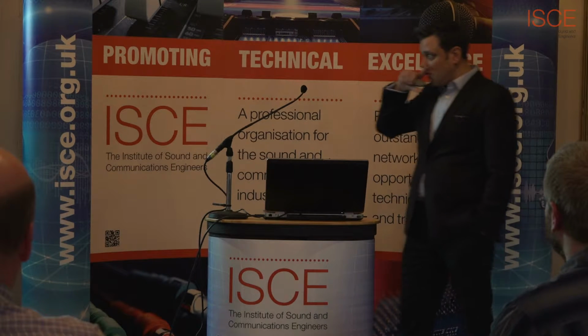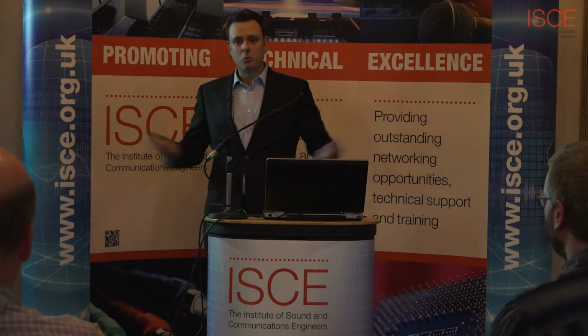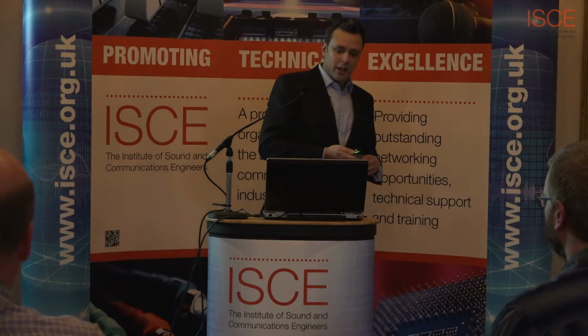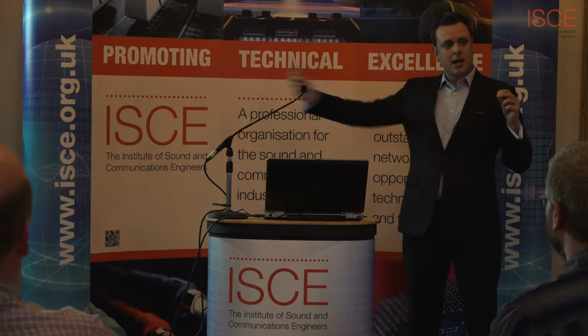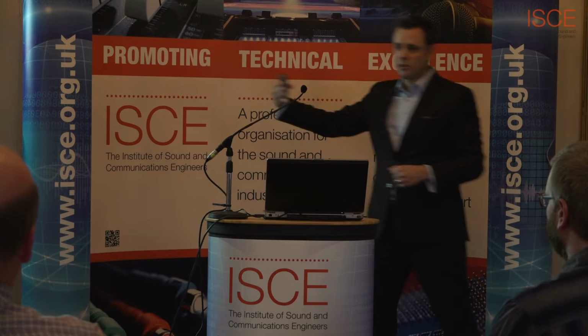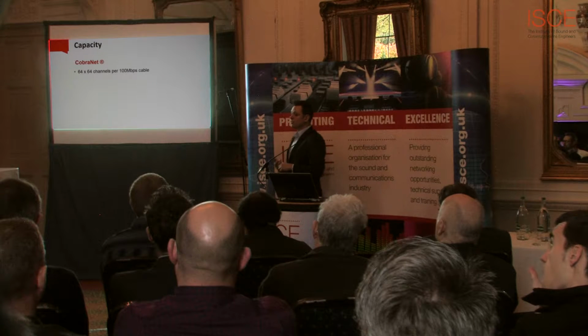So, when I started this talk, I mentioned how analog audio tends to be one channel per cable. If you wanted to have multiple channels, that's when multi-core cables come into the equation. So, capacity on the three protocols that we are talking about: CobraNet allows, in theory, on a single 100 megabits per second cable, 64 channels one way, 64 channels the other way. You could potentially get more on a gigabit, but CobraNet is not a gigabit technology.